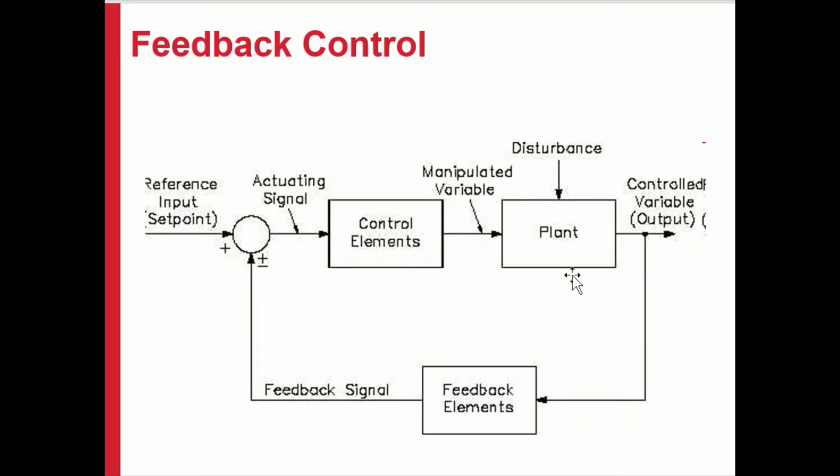The actual system we've got is a heating system, so this is heat energy going in here, gets heated up, and you get a temperature out here that's measured by a thermistor bead, which gives you the temperature here. We've got a desired value for the temperature and an error signal, which then drives the controller.